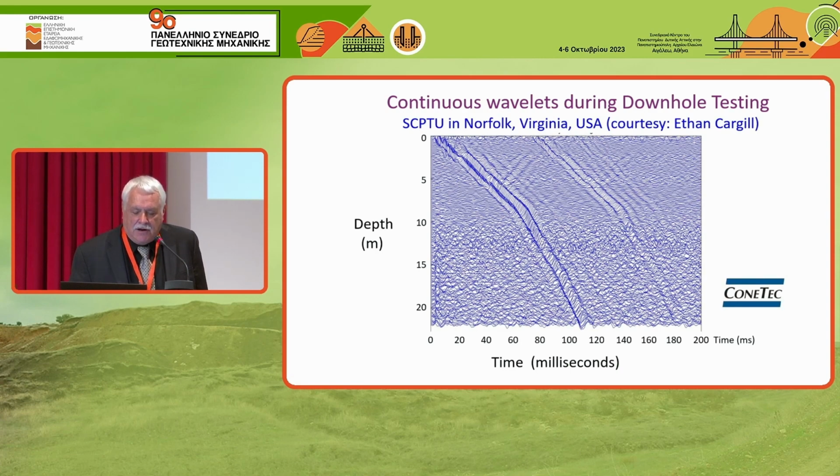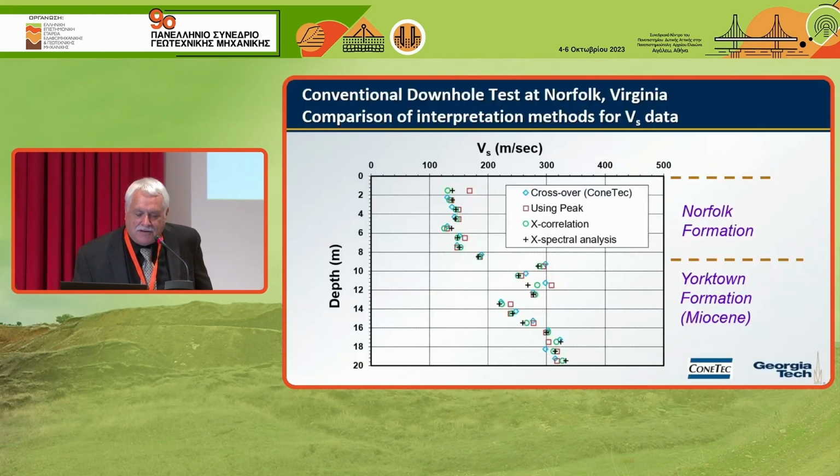They're very clear. What's also interesting is to see how in the softer material, it's much smoother in the noise coming up to the shear wave. And then in this lower formation, which has calcareous components, it's much noisier. So you can almost just use the pre-arrival of the shear wave to tell you what kind of soil type you're in.